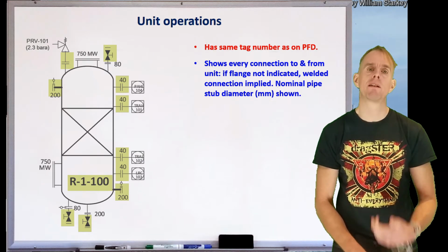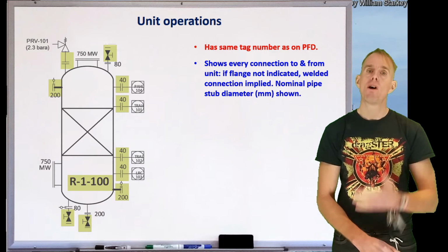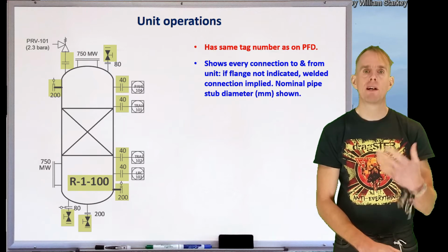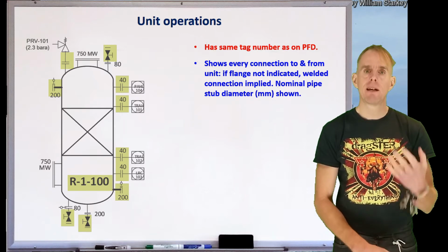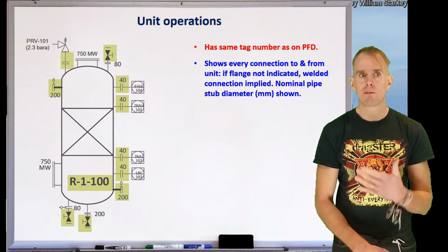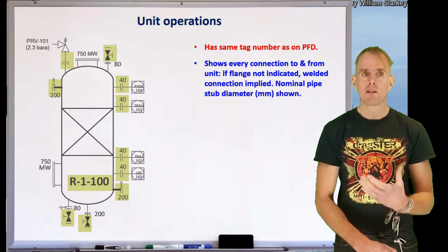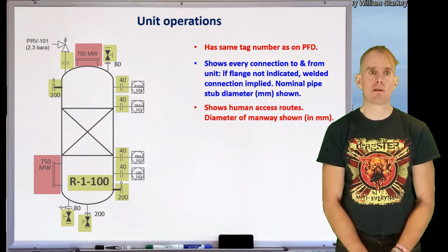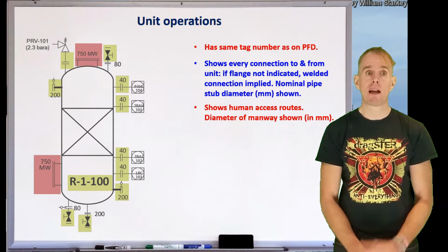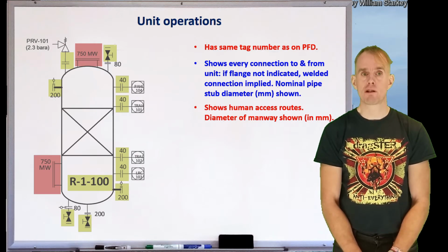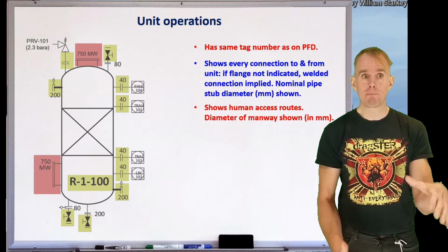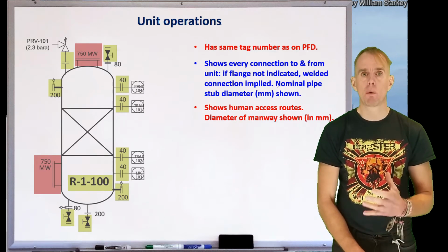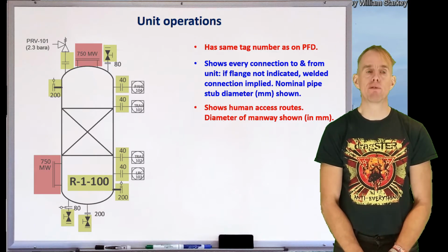And so what you would typically do is backfill with nitrogen, which in turn presents its own hazard, because once that nitrogen has removed the flammability hazard, it introduces an asphyxiation hazard for anybody who might enter. And so that leads us to these two personnel accesses, these two human access routes. There's two, because if this vessel is backfilled with nitrogen, we're going to put a fan at one, blow through air to displace the nitrogen once all the flammable service has been removed.